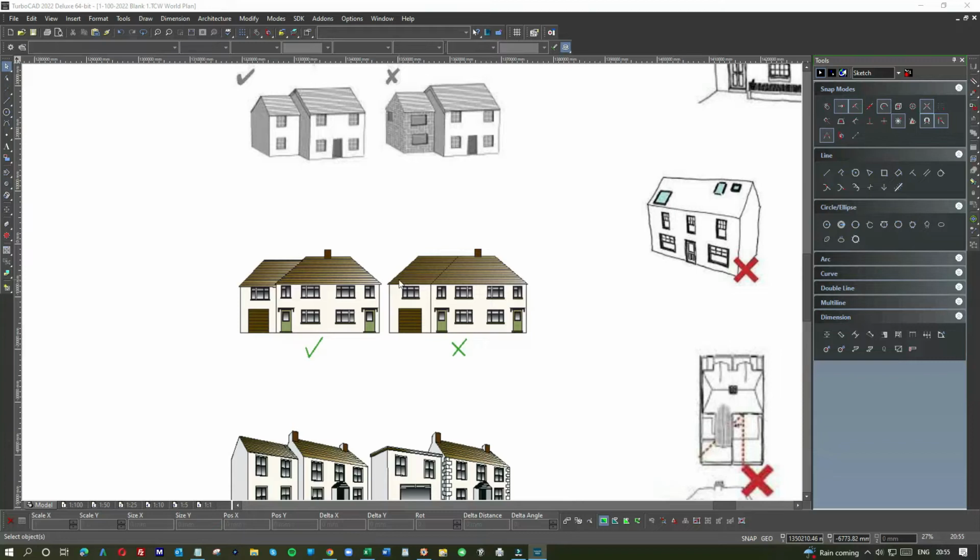Now that's not such a bad idea in some respects, but it's an absolute no-no. They've matched up the windows, which is good. But if we take it over to the left side, what they've done is they've made the two-story extension, or the garage with the room above, subservient by dropping the heights down, and because there's a line here, one has to assume it's set back a little. Even if this one wasn't set back, the roof needs to come down, because otherwise planning officers generally won't recommend it.